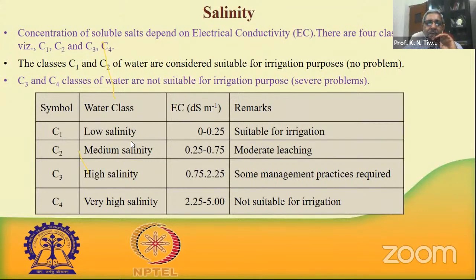Now here, for the salinity part, I am showing you this table, which I have taken from the slide of my video presentations. In this presentation, there are 4 levels of salinity given. You can see the salinity for surface irrigation system is up to 2.25 deciSiemens per meter. It can be used for irrigation, but drip irrigation can go further. One can go a little higher also. Yes, one needs to manage, meaning one has to keep flushing the drippers and use drippers which have less clogging problem.